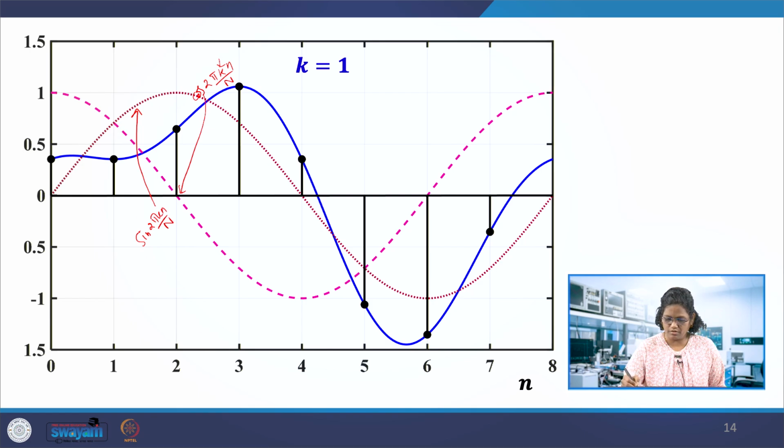If you see that this is completing one cycle up to this point, and similarly this is completing one cycle over here. So within the n samples, that is one cycle of the waveform related to the n and 2 pi. So the DFT is performing correlation between this sine and this, and taking the coefficient, and again performing correlation between this cos and the input signal.